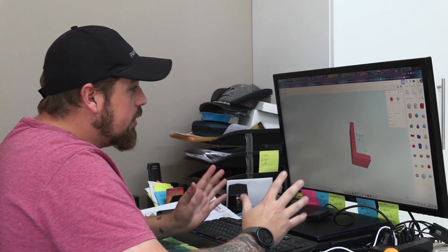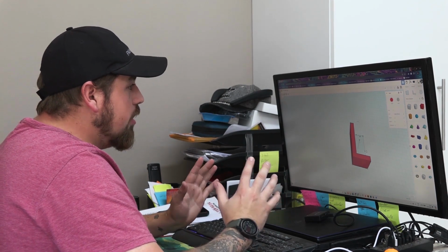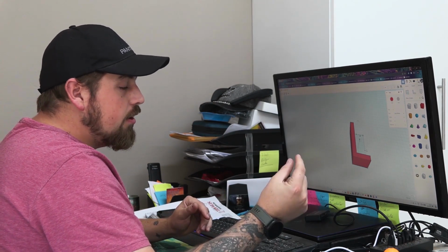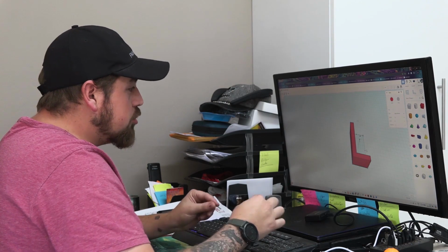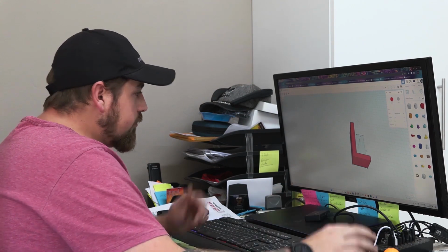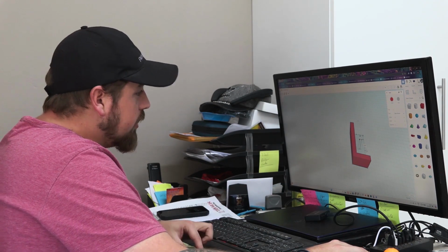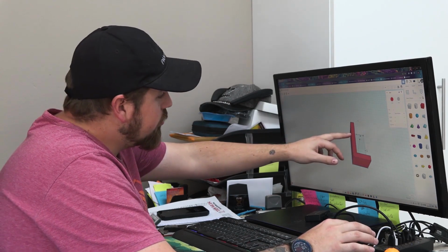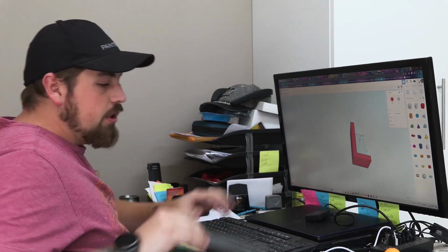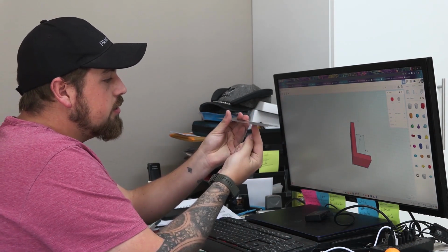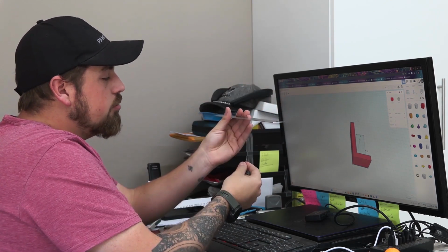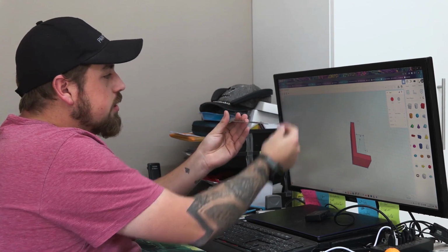Now, there are so many ways that you can do letter channel printing, but I'm going to show you the way that I understand it, and also depends on what LEDs you're going to use as well, whether it's strips or just single LEDs that you have to wire up manually. So for instance, I'm going to be doing the strip LED and making sure that we've got an entry here and an exit inside here, so that when you're doing a letter, for instance, you've got an entry behind the letter, then you've got your LED running along inside, and then it goes out again into the baseboard, which then can loop to your next letter.